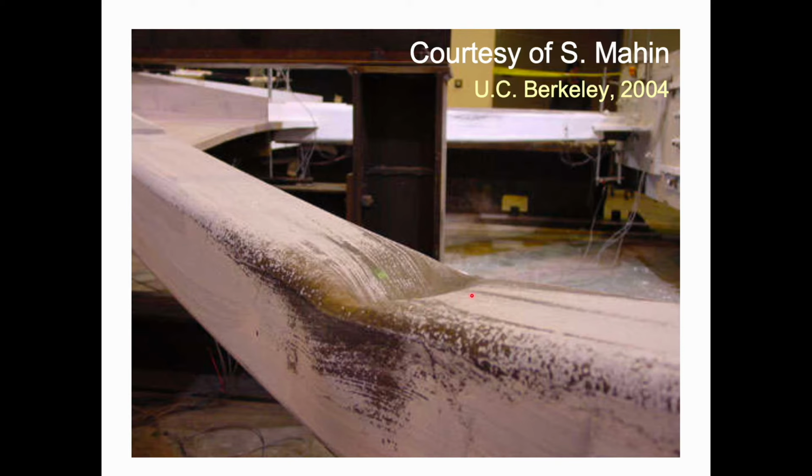The thicker is this section here. It means that it will be able to withstand that sort of buckling, and then it will come back in tension and then buckle again. If it's very thin, most probably it will break and fracture, and then the inelastic forces will move to other members of the frame, such as beams and columns, something that we do not want to achieve.